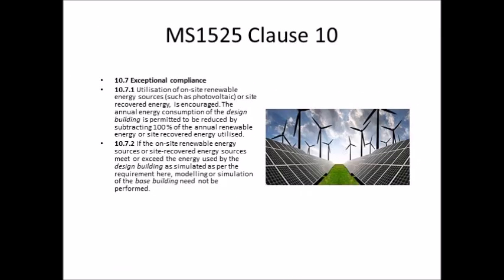Now, should your simulation show that your design building does not meet the requirement in MS 1525, that means your design building consumes more energy than your base building, then what are the options? There is another option that you can resort to. One is by using renewable energy, and this is stated in clause 10.7 under the title of exceptional compliance.